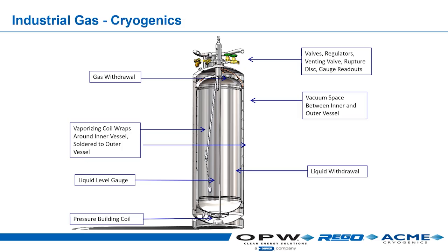A lot of times, I've seen bulk tanks where they've accidentally cut it, and then they fill it, and you can right away see they've got to undo it, rewrap it and start over again. So there's a science to that, and especially with trailers, because the two tanks are so big and long, it literally takes a whole shift to get a trailer inner vessel nested into an outer vessel, because you just have to go really, really slow.